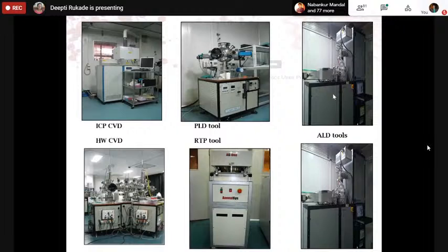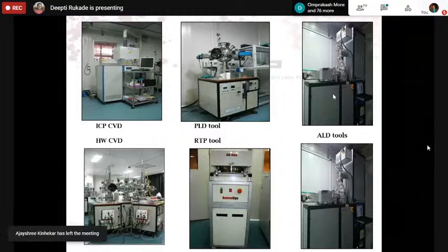Very high quality of deposition, or you can say a self-limiting reaction. After that, we ensure that whatever precursor we sent initially is purged out. To ensure that, we purge in an inert gas, mostly argon, and ensure that the remaining precursor, which was earlier purged in, moves out.